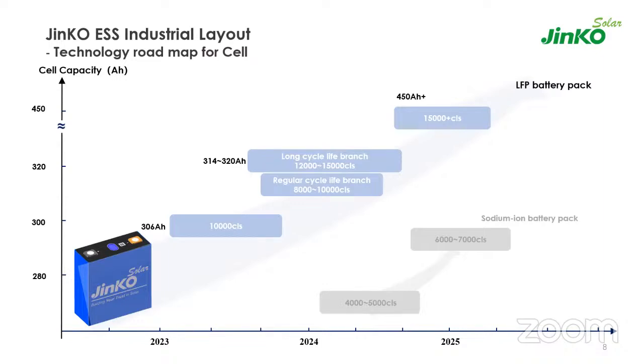Altogether, people have a perception, or a comparison, between lithium ferrous phosphate technology and sodium ion technology. But if we try to understand the number of cycles with respect to depth of discharge, the existing cell capacity is now standing at 3.2 volts, 280 Ah as the standard conventional product that is available. But now this is going to touch around 304 to 306 ampere hour with the same 3.2 volts. It can even touch around 10,000 cycles as the life of these batteries.